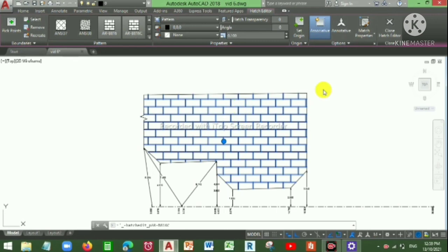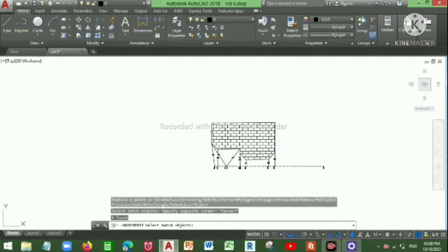Next, you can put on your index marks and your title box. You can put all your symbols and marks, put on your index, the graphs, and add all those details and features as required. And I recommend you draw a box outside, of dimension 40 into 25.5 centimeters, to enclose all your CAD drawings.